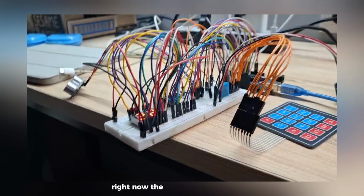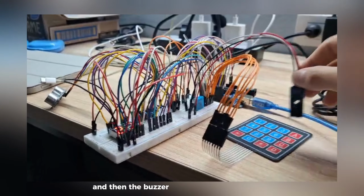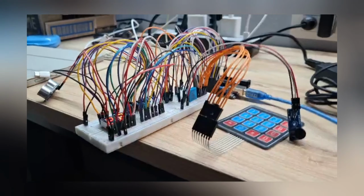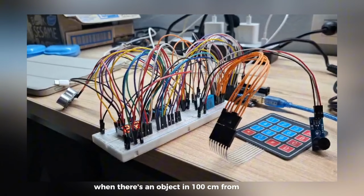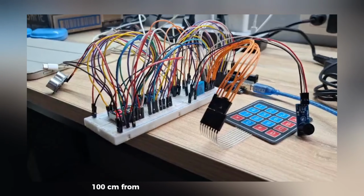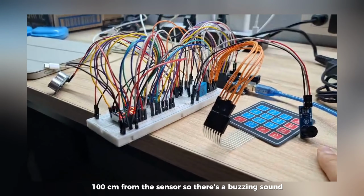Right now the ultrasonic is going to detect, and the buzzer is going to sound automatically when there's an object within 100 centimeters of the sensor, like this. My hand's within 100 centimeters of the sensor, so that's a buzzing sound.